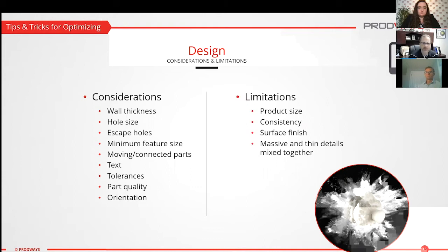The XY strength is consistent, the Z strength is similar, but orientation of your part is tied directly to the function. So being a heat-based system, I want to stress that again, that heat-based with orientation of your part, those types of things do go into deciding the optimal orientation.